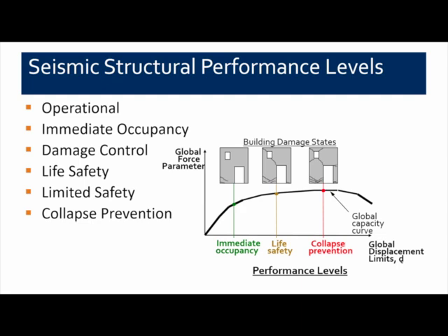So when we look at structural performance, as we just described, engineers have defined several levels of seismic performance of the structural elements that vary depending on how much damage we anticipate. So the best type of performance is what we call operational performance, and this is where the building, the structure, stays completely elastic with no damage during the earthquake.